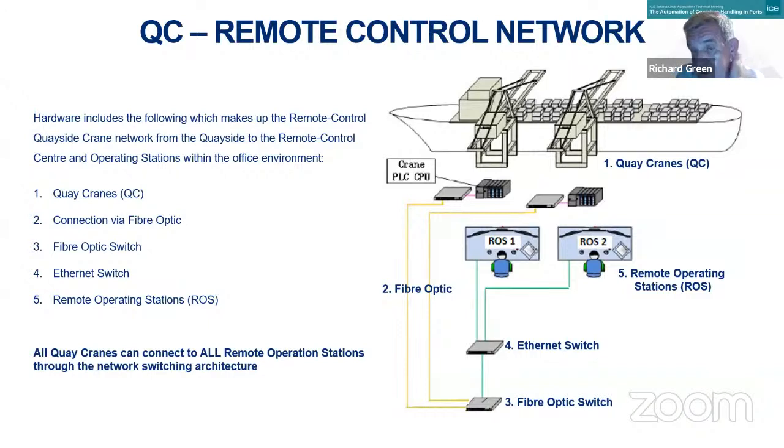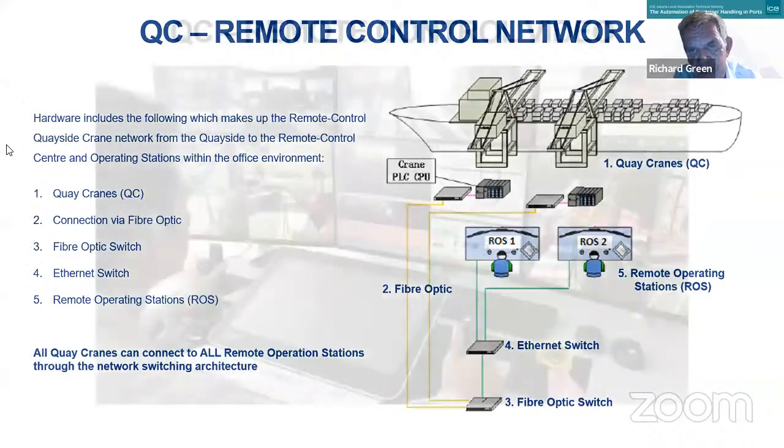One thing that you will need when you're designing a new container terminal is plenty of ducts. And however many ducts are in the design, always give yourself 100% redundancy, because for sure you'll need plenty of ducts to add in more cables.